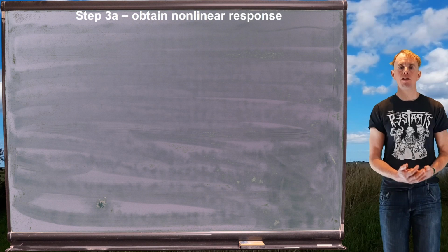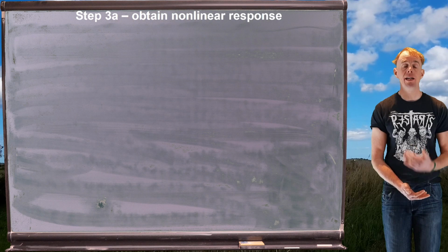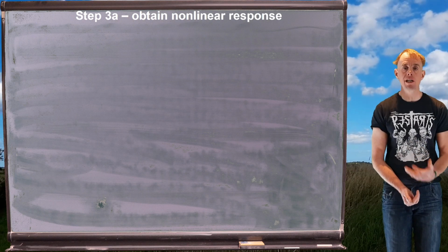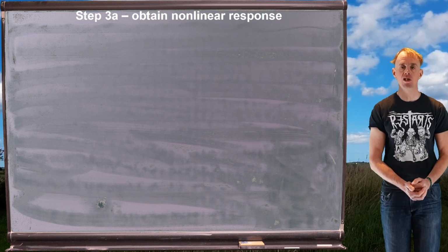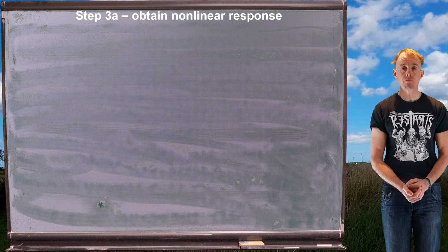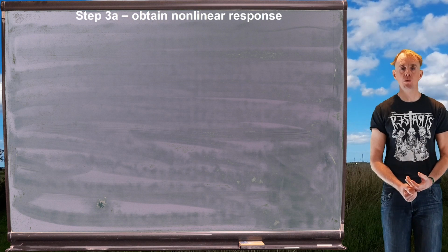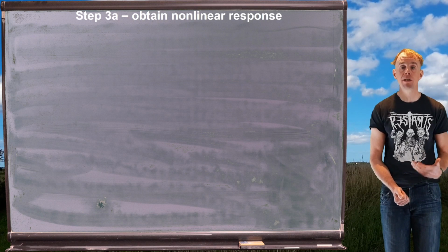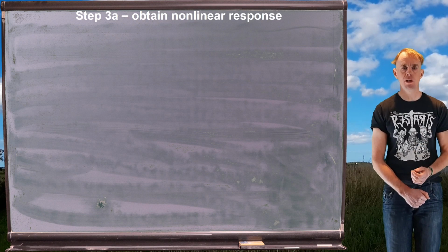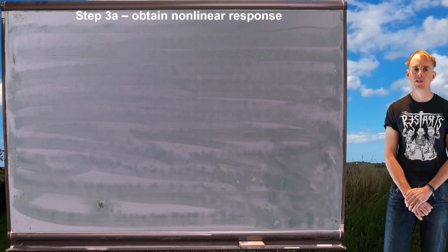We've seen we can capture this mathematically using one of two general approaches. We can have, for example, a damping function built into an integral constitutive equation. A strain-based damping function, for example, a Wagner damping function, should allow us to work out what that shear thinning in steady shear looks like. We've also seen that we can use an inherently non-linear constitutive equation. We saw the Giesekus equation was an example of that, and there are many more examples of more complex non-linear viscoelastic constitutive equations. We're going to take the first approach. We're going to use the damping function approach in this analysis.